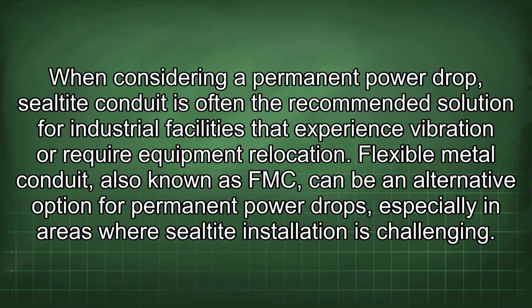When considering a permanent power drop, Sealtite conduit is often the recommended solution for industrial facilities that experience vibration or require equipment relocation. Flexible metal conduit, also known as FMC, can be an alternative option for permanent power drops, especially in areas where Sealtite installation is challenging.